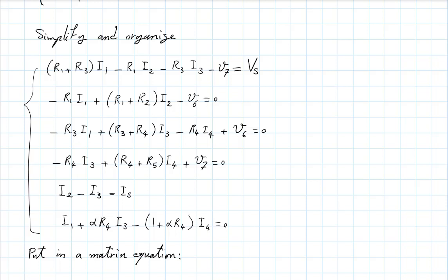Conversely, if you had a circuit that had just one big loop with 20 elements around it, and you wanted to solve for all the node voltages, you'd end up with a huge matrix. It's not going to be a difficult problem, but it's going to be bigger. Whereas you could write one mesh equation, find the mesh current, and then, if you want all the element voltages, work backward and find those. Depending on how many nodes versus meshes you have, one approach would be computationally easier, at least at the first step.